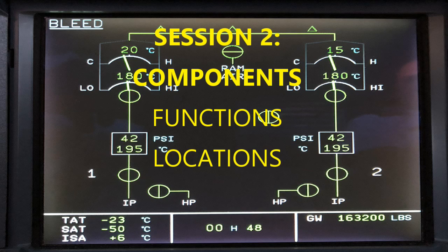This bleed load valve has a position indicator switch, and it's going to be transmitting signals to the ECB so that it can get that information about the valve position. Because remember, we're talking about being able to monitor valve position, temperature and pressure. So here we have the information signals getting sent to the ECB about valve position with this particular one, the load valve.